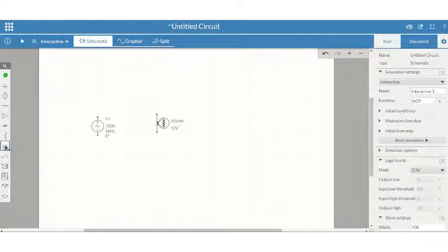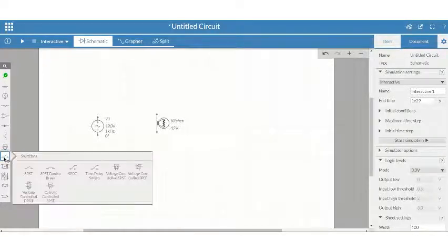You can see underneath the symbol for a light bulb, a common symbol for a switch. And the switches that we'll be using here are called SPST switches. That stands for single pole, single throw, as opposed to things like SPDT. You see that symbol here where it is a single pole, double throw. An example of this, something that would use an SPDT switch, would be if you have something that has a high and low setting and you're switching it from high to low. When things are just on and off, it's pretty much a SPST switch.